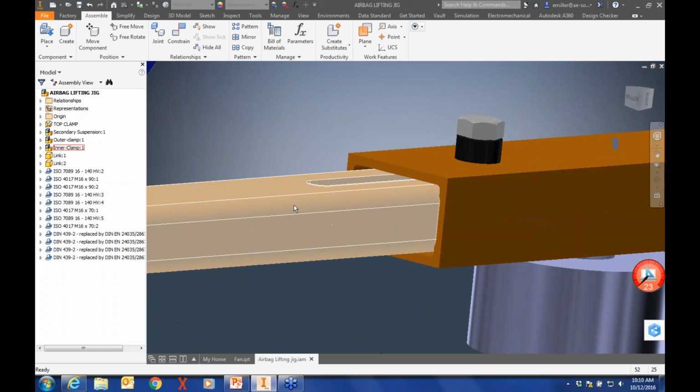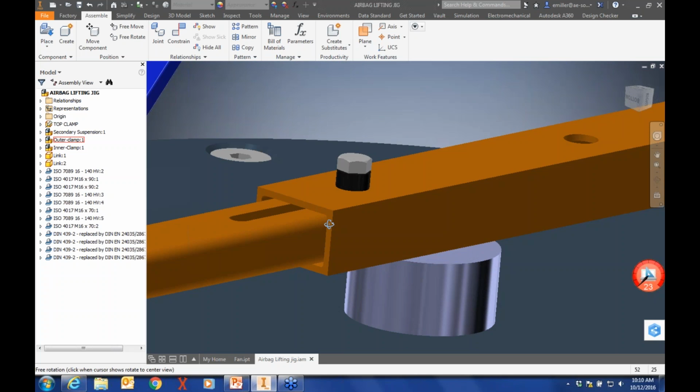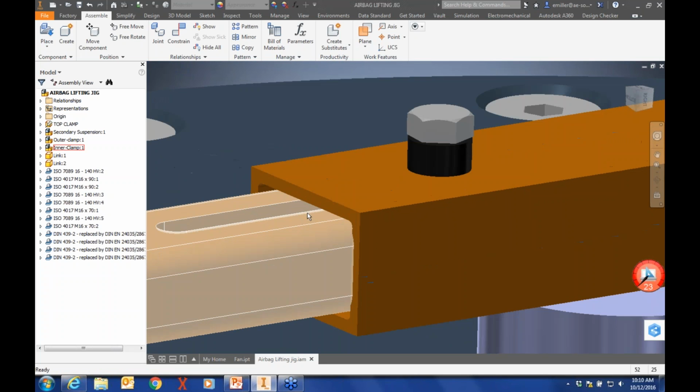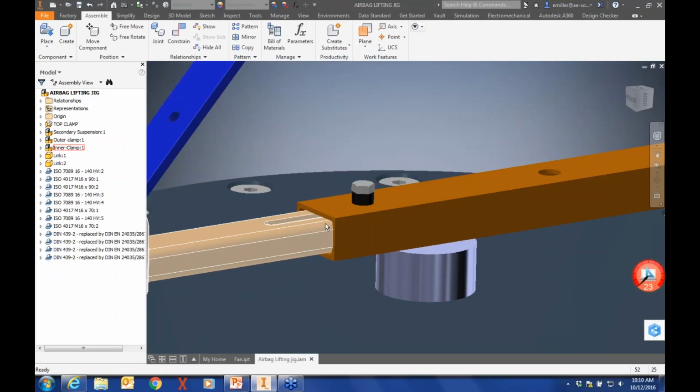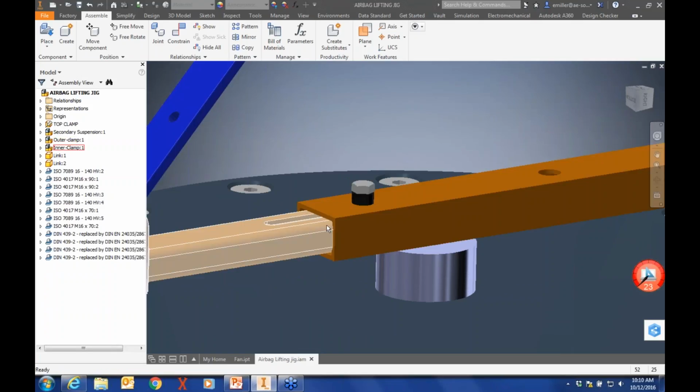All right. So first thing we can take a look at is, can we get rid of some of the rounds? Whenever you have rounds in a model like this, it creates more mesh elements. So if we can get rid of the rounds, a lot of times it'll improve the overall size of your mesh. But obviously you want to be sure that there's not any stress risers there.